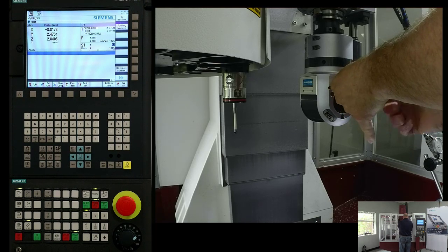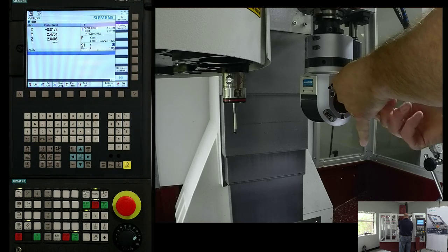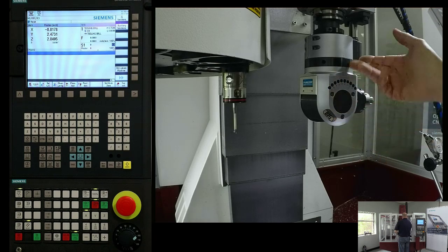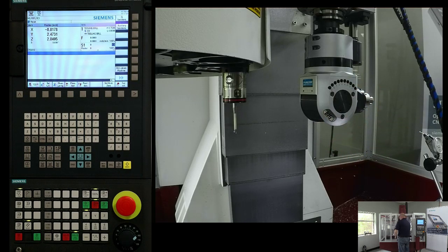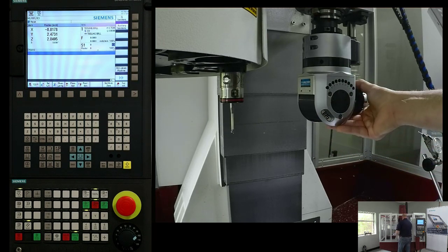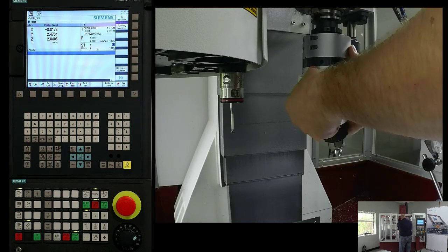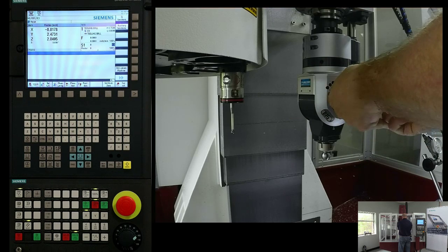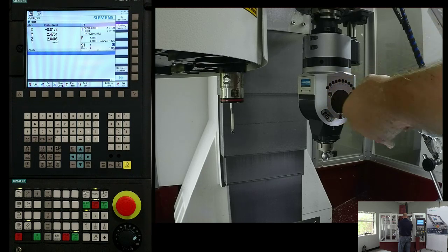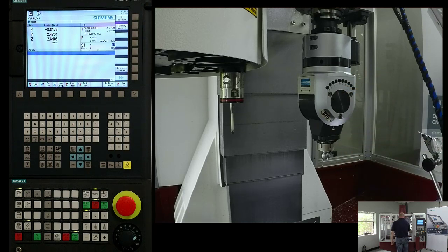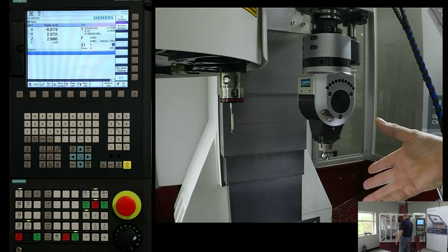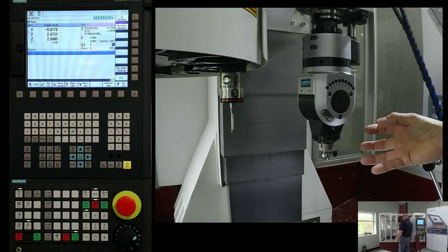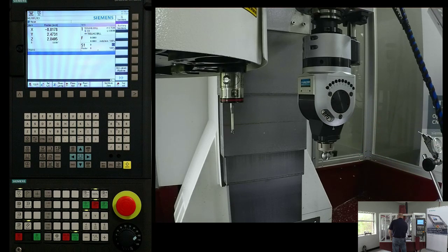So here we're going to loosen it up. To adjust this head, you loosen up all 6 bolts around here, front and back. I already have these loosened just for time's sake to speed things up for us a little bit. And then I'm going to move the head down to a vertical orientation. And then we bring the appropriate indicator in. We went through this in a lot more detail certainly in our first video. But now my head is straight. And certainly if I was going with real hard numbers here, I would make sure everything's tight, everything's settled in before I take any of these measurements.